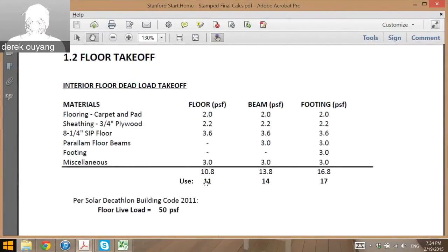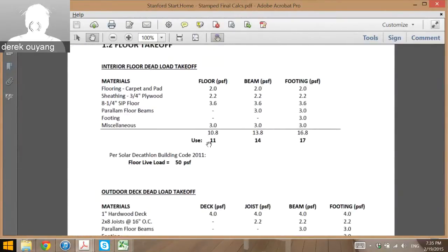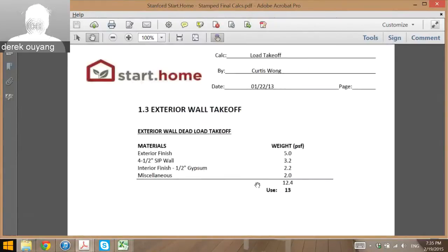The reason they're showing 3 different columns here is just because when you design the floor, it doesn't care about its own self-weight as much as the next part and down. So this is going down the load path to get more and more weight. So they were just doing that all at one point. And you could maybe consider doing that in your gravity load spreadsheet, because we're going to be designing by load path. So you start with the slab, and then once you design the slab, its weight goes right back into the gravity load takeoff, and it gives you a new WU or W for the secondary beam, for the girder, for the columns, right? So those all sort of add back up together as you go down the load path. That's what these columns mean.